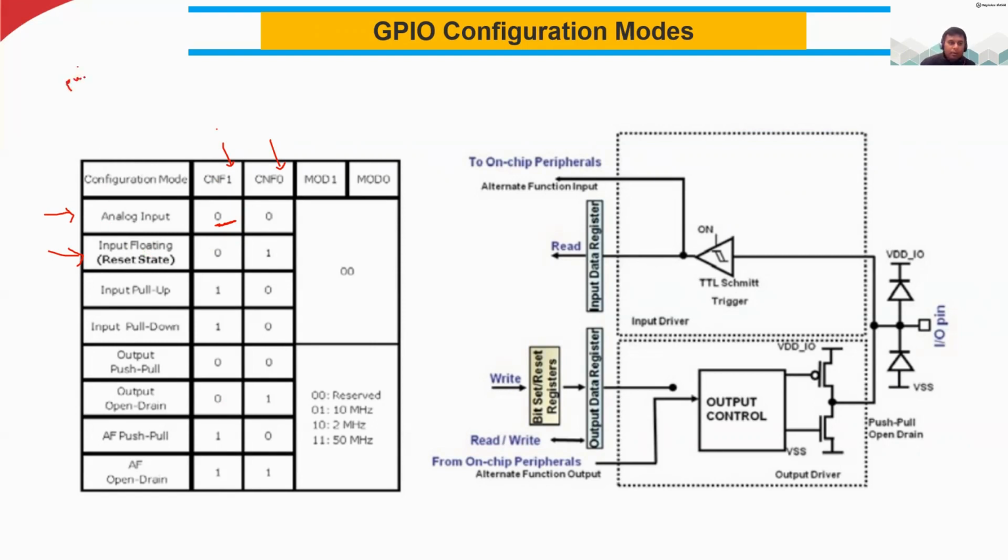You will use a pull up resistor. I mean, you are not the hardware designer here, but normally hardware designers will use the pull up resistor and pull down resistor. So what this will do, if the IO pin is in the floating condition, if it floats, float means what? It's not logic 0, it's not logic 1. So it's in between. Logic 0 is 0 volt, for example, and logic 1 is plus 5 volt. So this is just near the threshold voltage level.